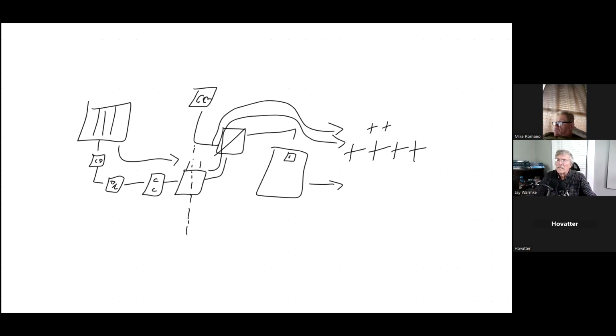So we size the inverter. The main question: how do we size this inverter? It's based on the maximum power draw. So if I can turn on, let's say, 3,000 watts in combination of all of the loads whenever I'm turning things on, then I need to have at minimum a 3 kW inverter to handle the load that's being pulled through it.